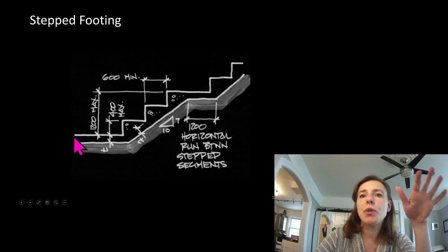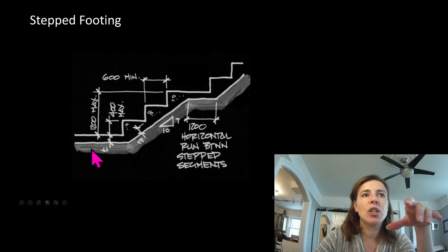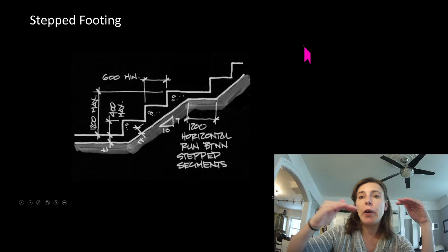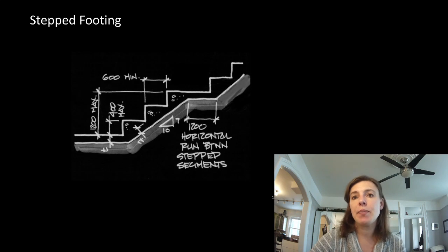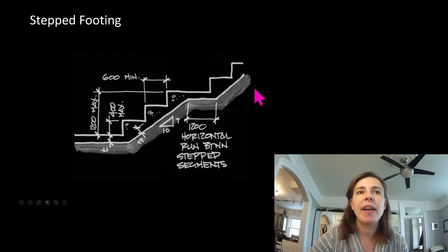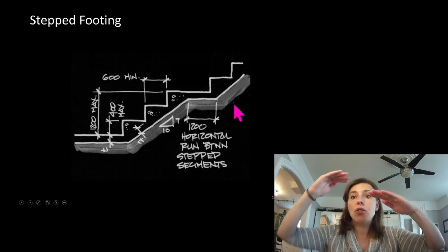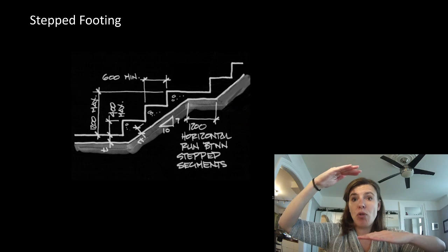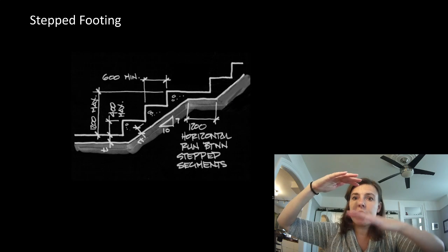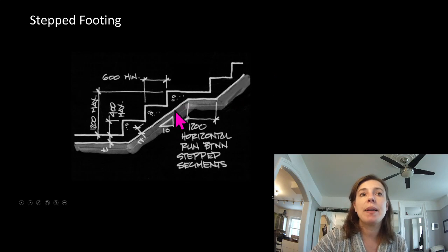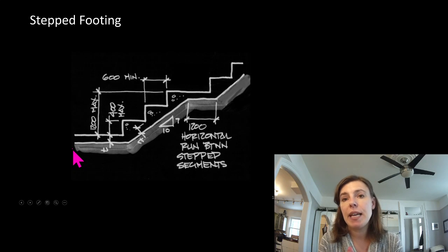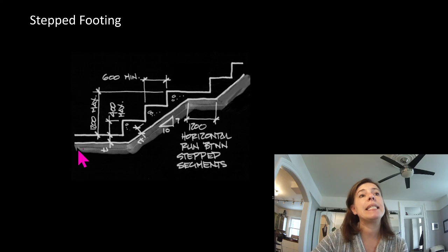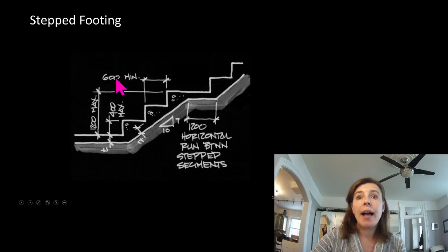Stepped footing. I showed you guys this earlier in the term. If we have to drop our footing down because maybe we have a zone with no basement and we drop down to a basement, or maybe we have a sump pit or an elevator, we can't just do a straight drop. This load starts to damage this load. We have to step down our footing. I uploaded at the beginning of the term typical details for you guys, and you can go take a look at those and see this detail worked out in great detail for the stepped footing.